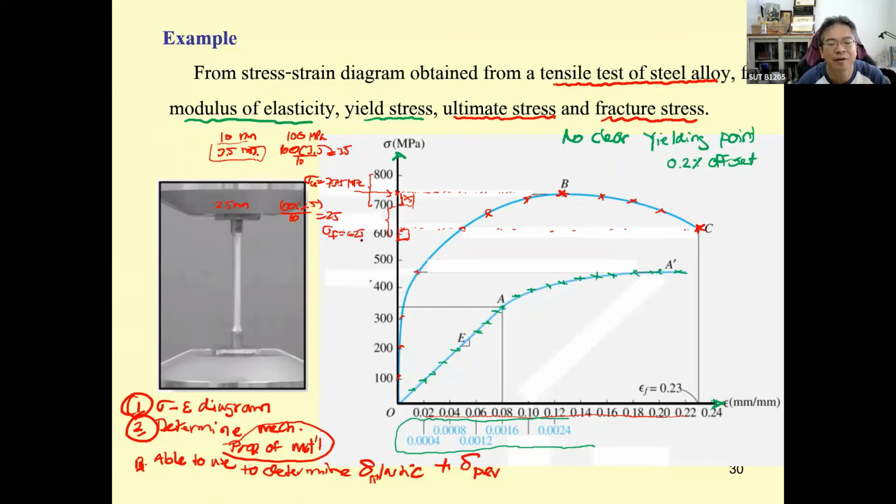Okay, 25 megapascals. And then for the yielding, this yielding is going to be determined based on the lesson above. Which scale do you think to use? You cannot use the rough one; you finished looking for the rough one. So you're going to use the fine scale. When you use the fine scale, 0.2 is the same as 0.2 divided by 100, so it's going to be 0.002.